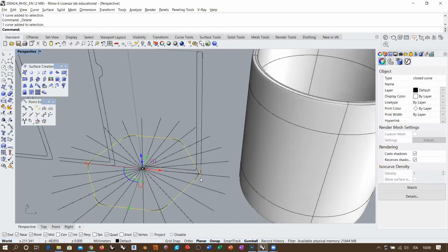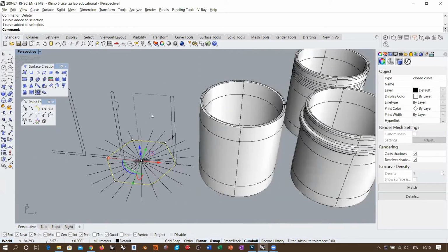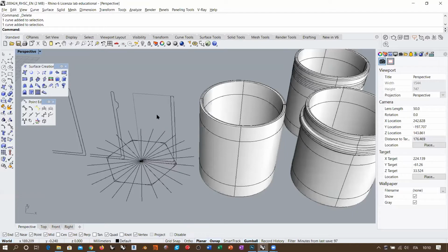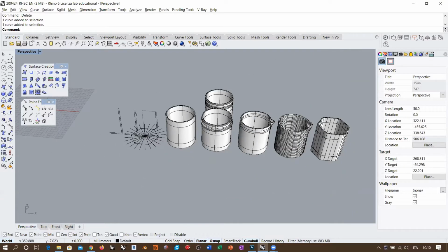Like if you create a revolve with a hexagonal polyline, then you will have kinks on the sides, on the vertices of the hexagon. But if you smoothen the curve and create it with a degree 3 curve, which by default has no internal kinks, and so no internal discontinuity, be it visible or invisible, then you will get a perfect degree 3 smooth surface, okay?